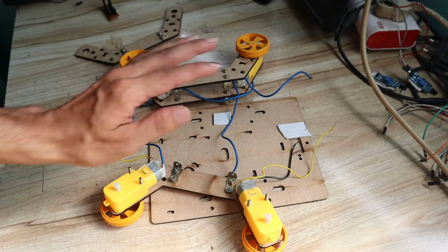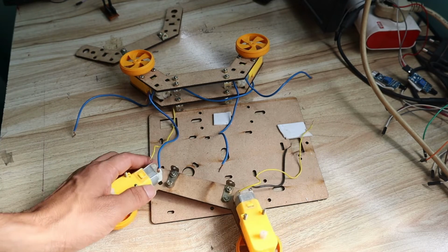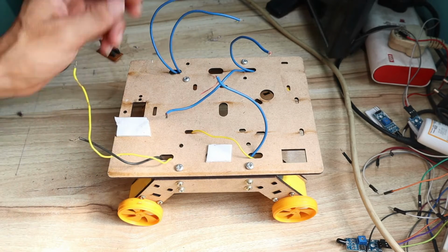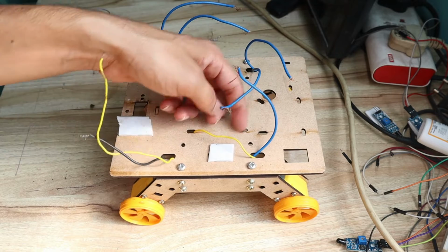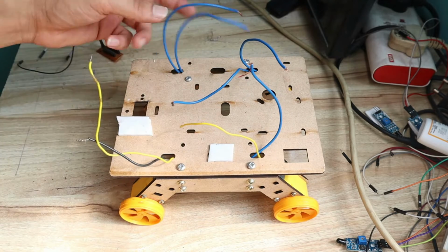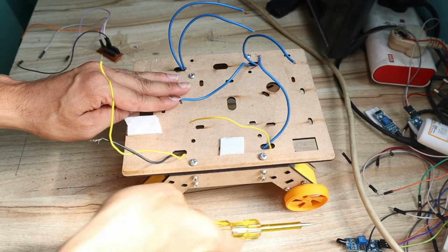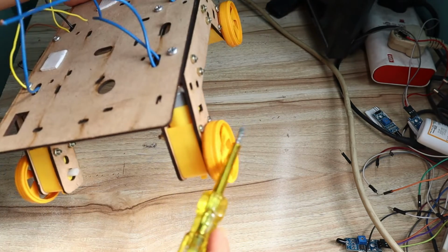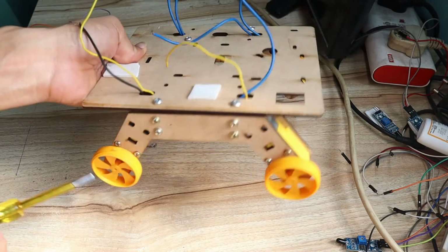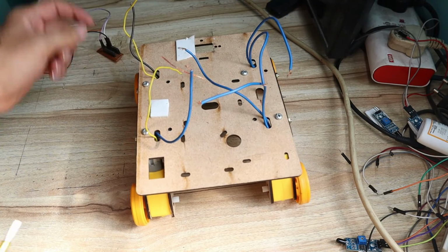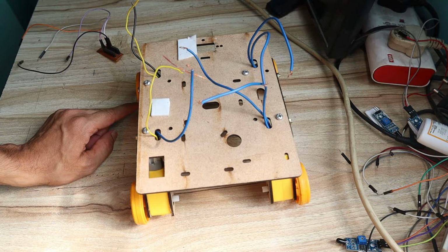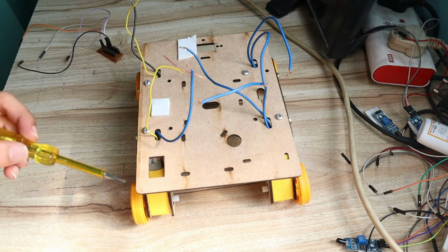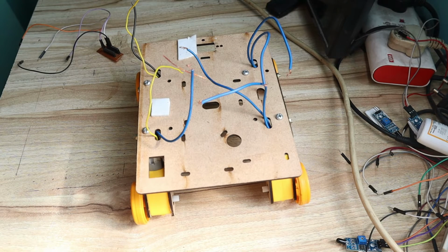Now quickly I will connect the chassis and bring these wires up. Once you have 8 wires for your 4 motors, you can see that from my chassis 8 wires are coming. Now we have to find out the direction of the motors. You can see there are 4 motors, and these 2 motors are for the left side, these 2 motors are for the right side. When I give the supply, these 2 motors should rotate forward, and these 2 motors should also rotate forward. So the direction should be the same for each motor. How to find the direction, we will see now.